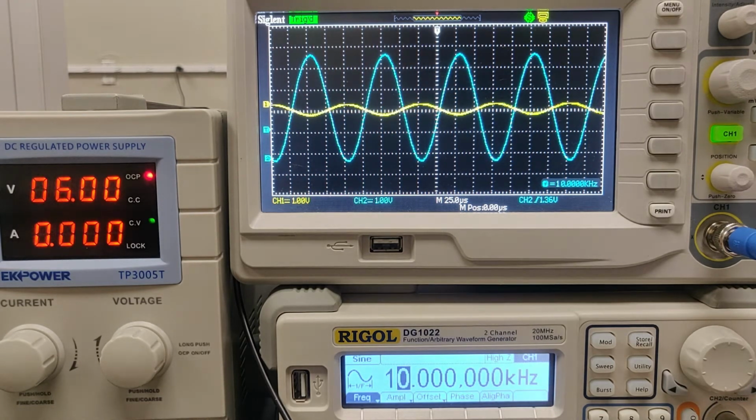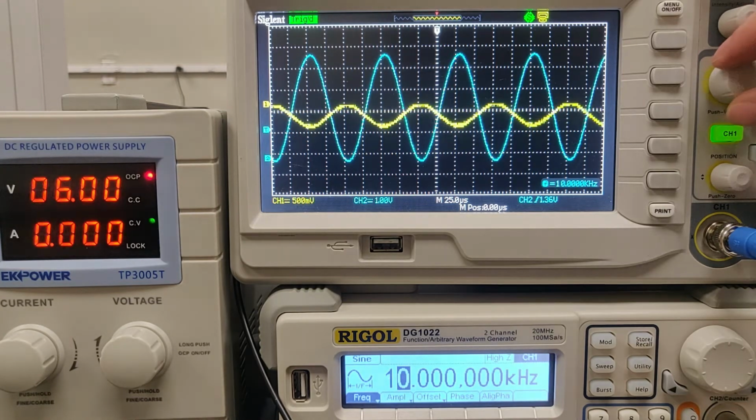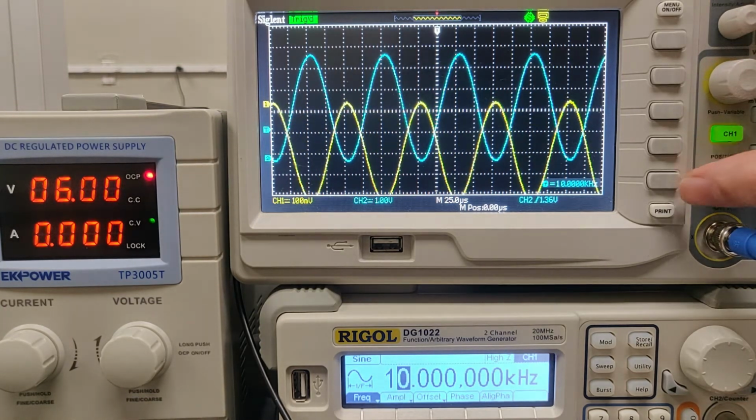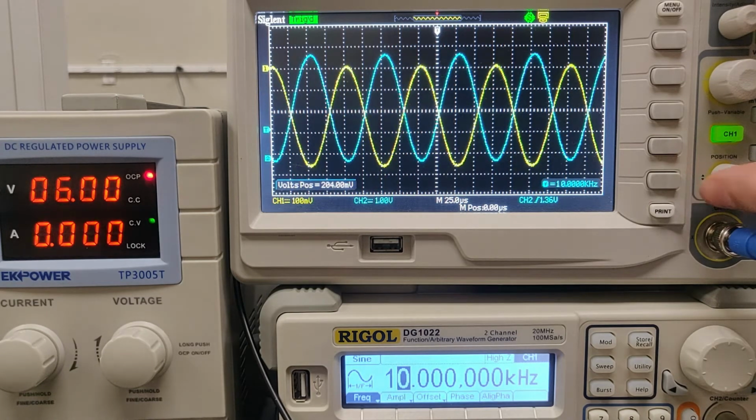You can see that our output signal is roughly 10 times as large as our input signal, and it looks like it is 180 degrees out of phase. So our op amp is both inverting and amplifying our signal, as the name suggests. So in this next part, we're actually asked to measure this phase shift.